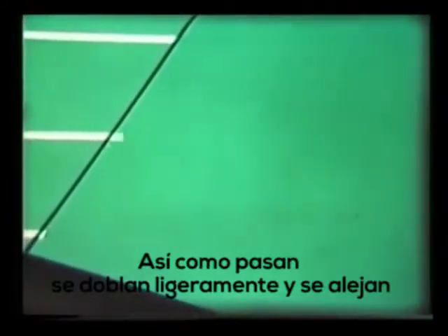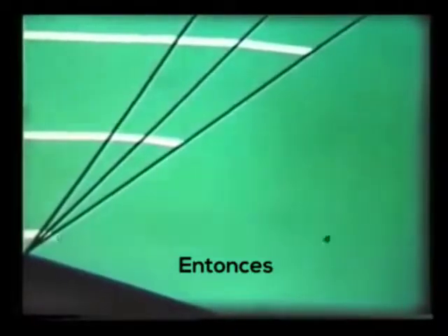As soon as they pass it, they bend slightly and move further apart. The influence of the corner is at once felt along a new Mach line, and the streamlines bend again, and so on. An expansion at a corner can be looked on as a series of tiny changes in direction, pressure, and speed.